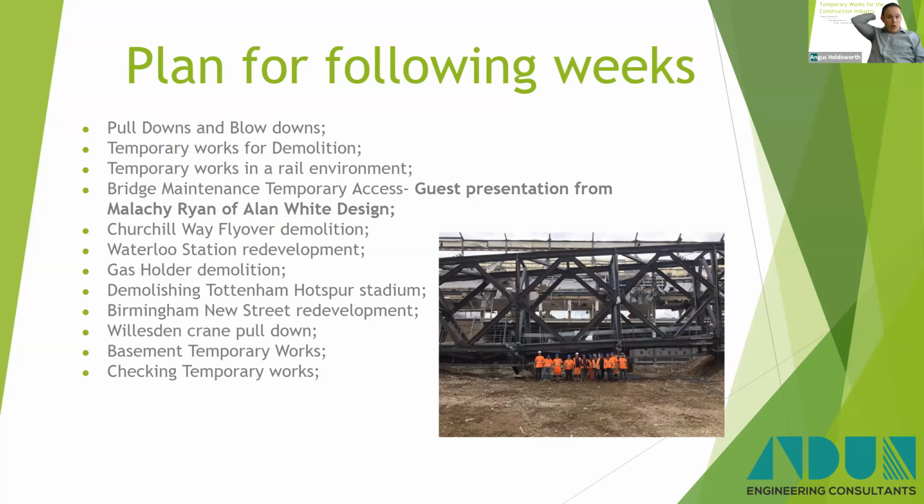I think the guidance is quite clear that all sites, where there's temporary works involved, should have a TWC. Now, the level of experience and competence of the TWC obviously has to be tailored to the job they're doing. So if it's a simple job with just some basic scaffolding and basic hoarding, then the skill set the TWC requires is not that high. Whereas if it's a complex job in London, or any other city centre, with multitudes of temporary works involved, then you will definitely need a TWC. You might need a TWS to stop the TWC being overloaded, and the competence required of the TWC will be much greater.